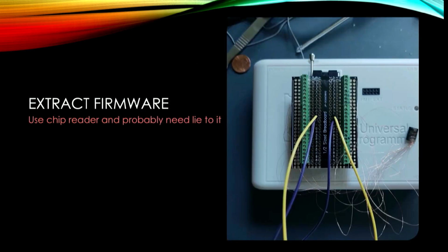Okay, so like I said, we wire this thing up, we drop it into a reader, but I already told you none of the readers can actually read these things. Manufacturers of chips don't create new chip silicon for everything underneath the sun. What they do is they just put it in a different package. So then you have to figure out what of all the chips that they produce is most likely to be what's underneath the hood of this one. And you do that with no data sheets, because most of these don't have data sheets.